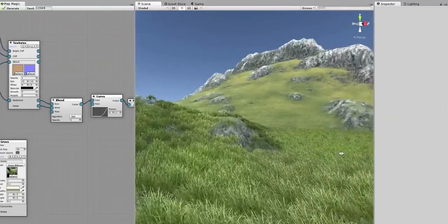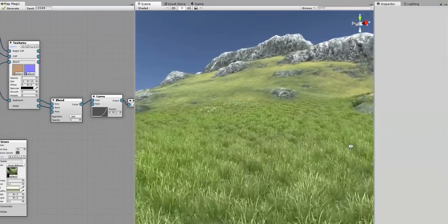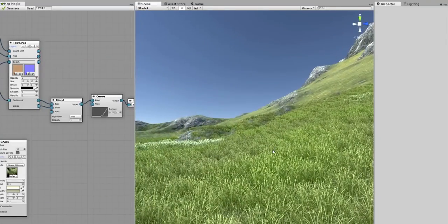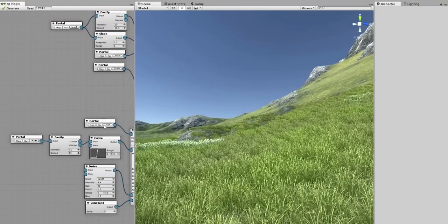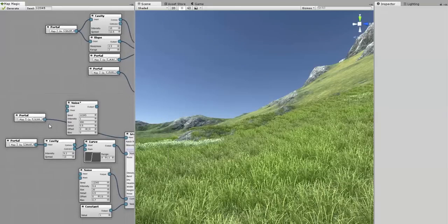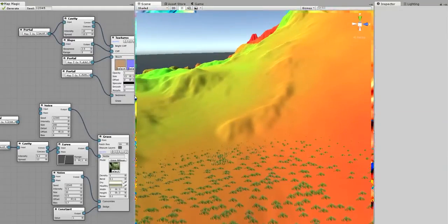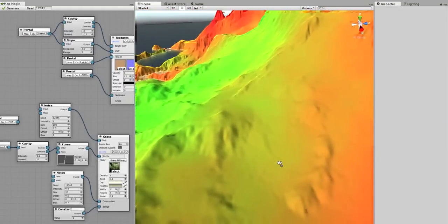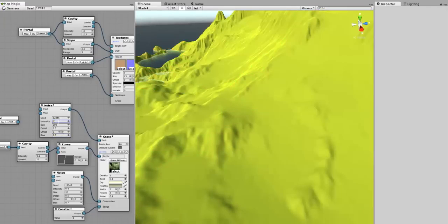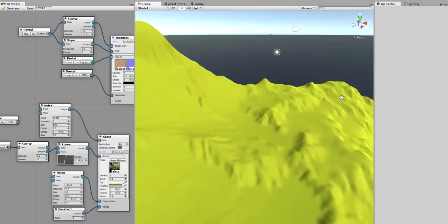The next thing I'm going to do with the grass is removing its uniformity. You see there are endless planes of it, and I'm going to thin it out with some bald spots. I'll use noise generator for this. Now let me show you one interesting thing. I'll switch to the noise preview, and I will set the bias to 0.5 and intensity to 1. The noise will become homogeneous. I hope it will help me to explain.